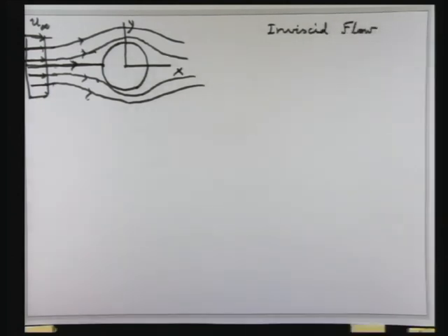Now in your preceding lectures, my colleagues have talked about the no slip boundary condition, etc. A simple minded way to think about it is that a fluid sticks to a wall because of viscosity. So if you have a viscous fluid which satisfies the continuum hypothesis, and you have a solid wall which is at rest, then the fluid particle at the wall will also be at rest. But if it is an inviscid fluid, then it can slip along the wall.